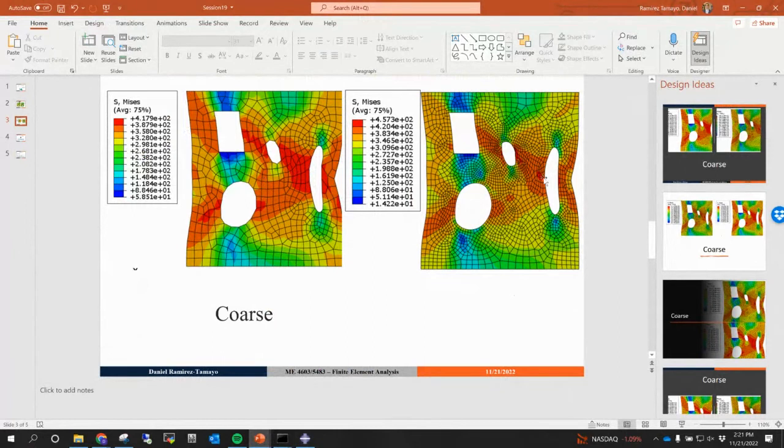It is not. It's only this region in here. In between, the stresses are not that high. However, the magnitude of the highest stress here is 457, whereas in your previous job, it was 417. Okay, so the magnitudes are wrong in our first job, and the distribution of the colors is also wrong.